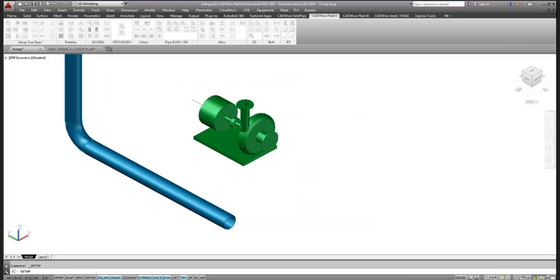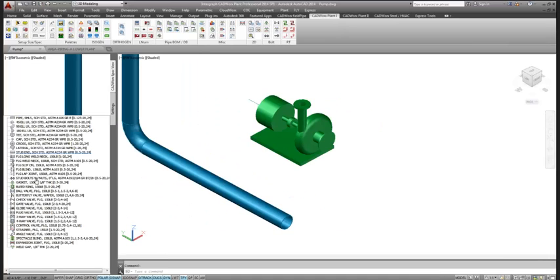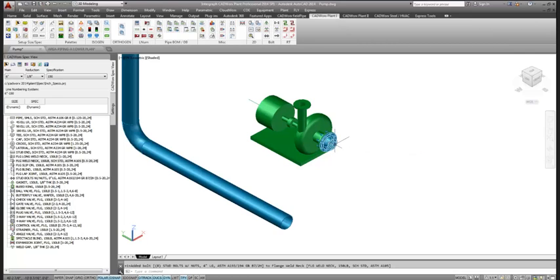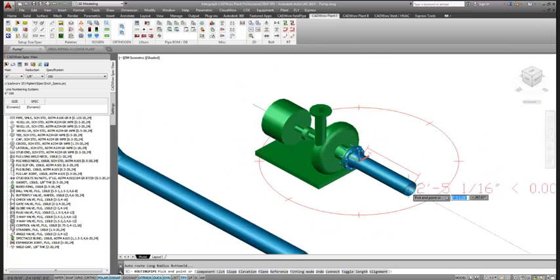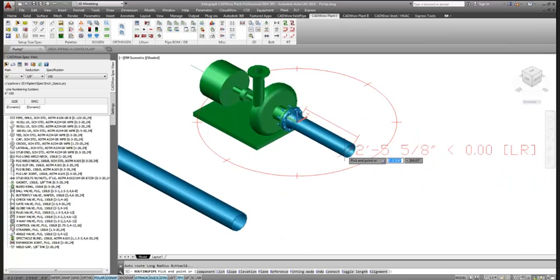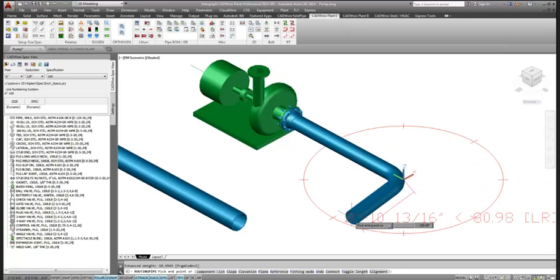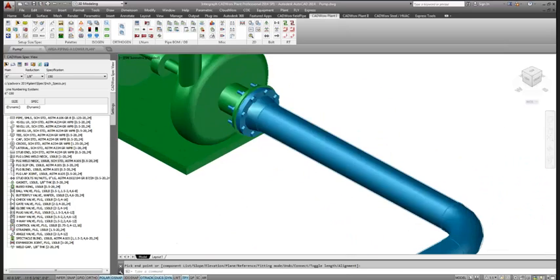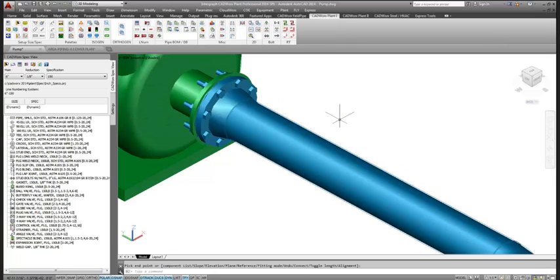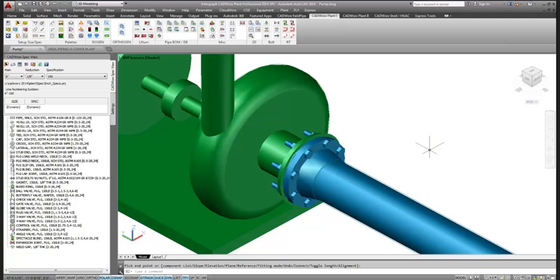So no, they are. So what I'll do is I'll just come in and say I want to go ahead and insert a flange. And so you see that kind of automatically displayed there. And so it'll let you just continue on routing if you needed to do that. Okay. So it'll automatically give you that connection. It'll give you those welds, that new gasket that you have in CADWorx 2013. So that's the new enhanced connection. So again, the plus grip will be available through that nozzle attach if you need that.